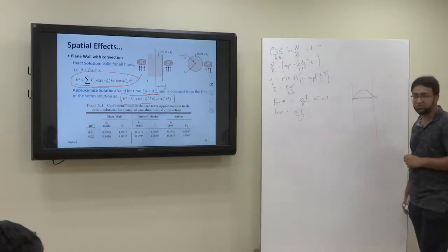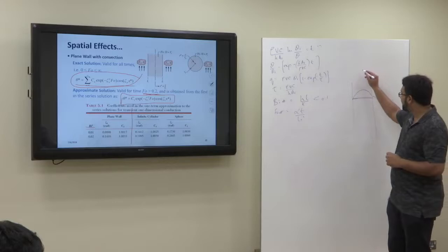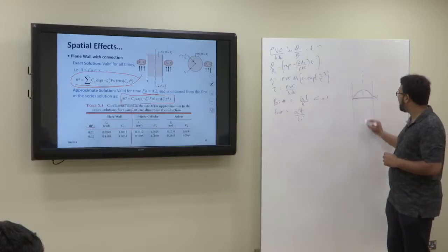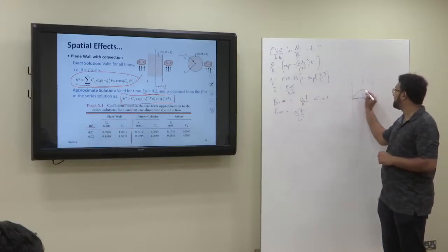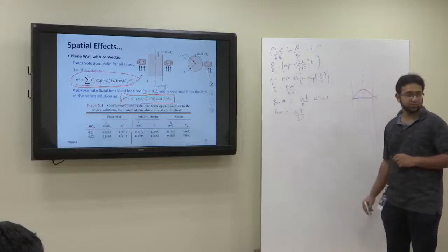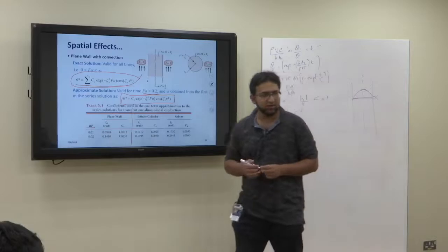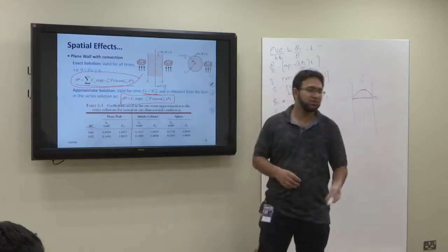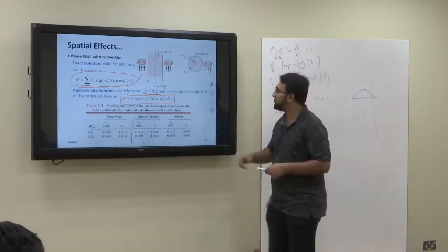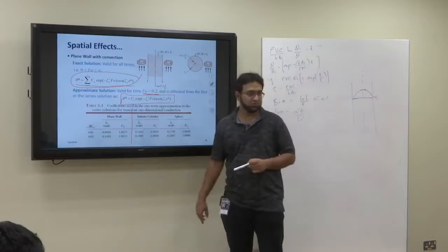Whenever we have a temperature gradient, we will have a specific plane where the temperature gradient becomes 0. That specific plane could be considered as an adiabatic plane, and that plane we consider as our reference point, the plane where we put our x0.